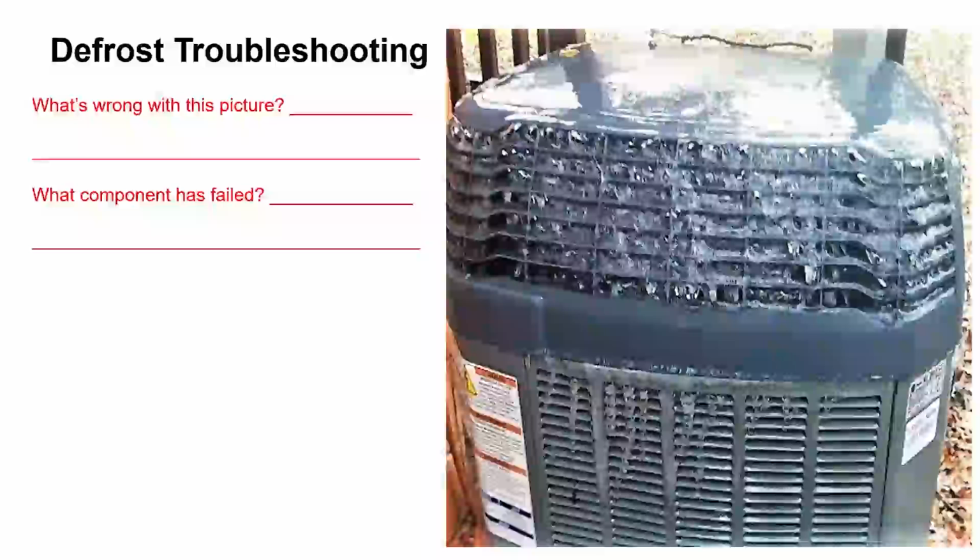Now, this was a fun picture from one of our field trials. What's wrong with this picture? Well, we had water draining right onto the unit. And as you can see, it froze up and basically blocked the airflow of the unit. So what happened? It froze.